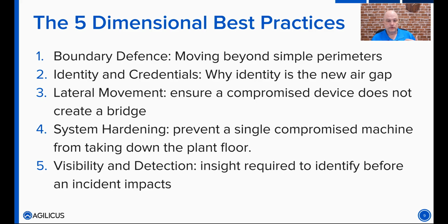This might involve investing in a testing environment so you can test out your change. This might involve testing some HA or some availability methods so you can upgrade it live. And the third category is where it really gets hard. And this is the process. This is something where patches get really thin when you start talking about industrial equipment. It's not like there is a big CVE catalog and a Patch Tuesday Windows Update server for a Rockwell PLC.